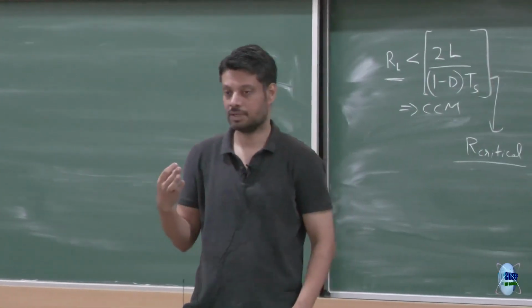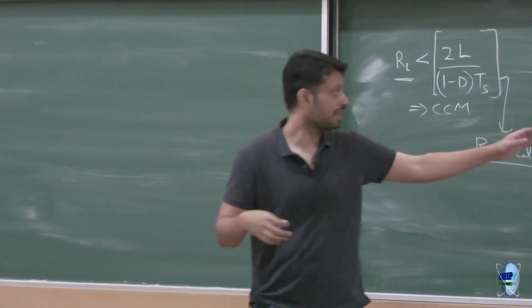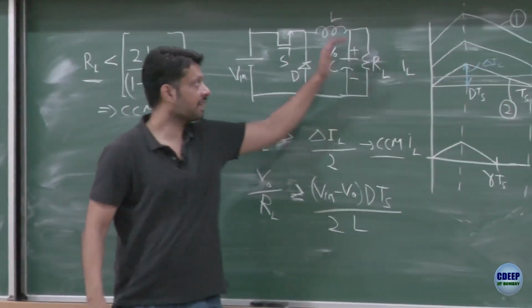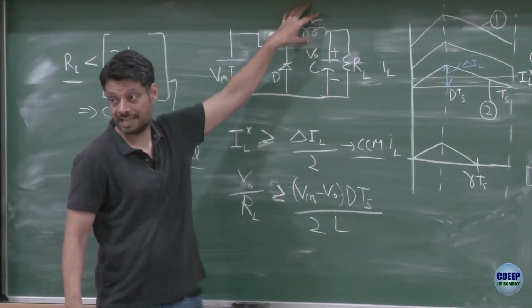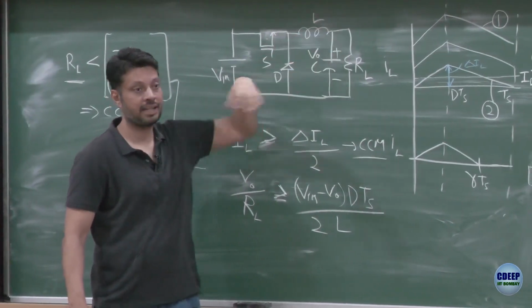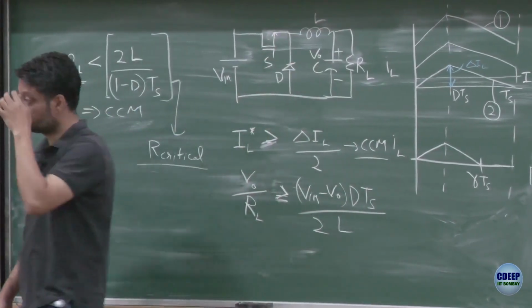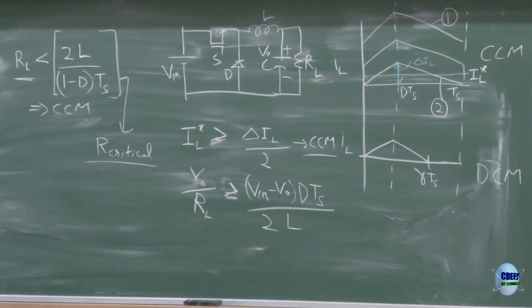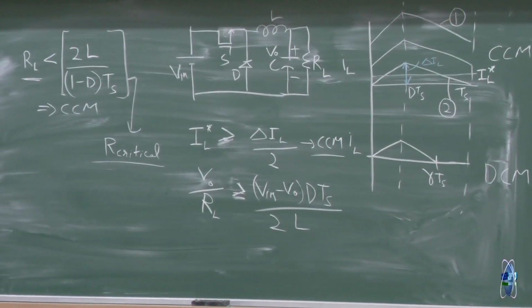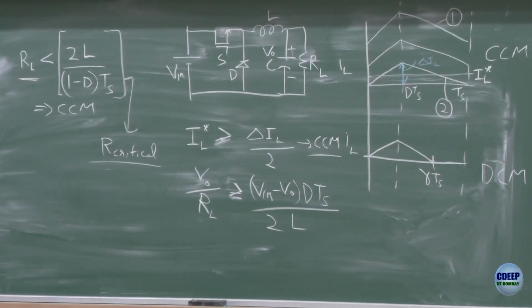It remains the same, right? Because the ripple current is the same, the average current anyways goes from here to here. Since the ripple current component is the same, that's what is flowing here and that's what is leading to the ripple in the voltage. So that remains same, means ripple in the output voltage would remain same. Anything else?